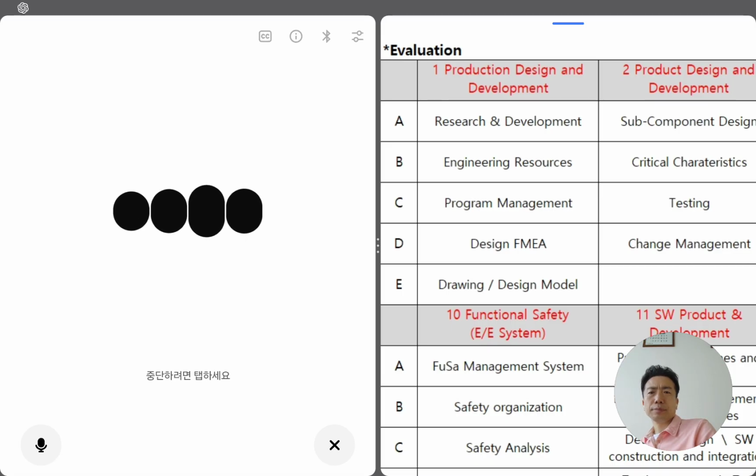3. Field issues, complaints, dispatches. If a product fails in the field, customer complaint, warranty, recall, or dispatch, then ideally that cause should have been considered in DFMEA already. If it wasn't included, then the company should update DFMEA to add it, so the risk is covered for future projects. A good DFMEA is one that captures field issues as lessons learned and prevents them from happening again.